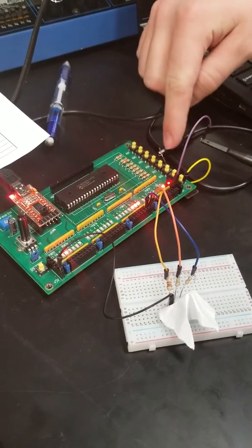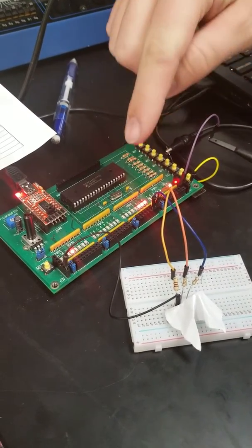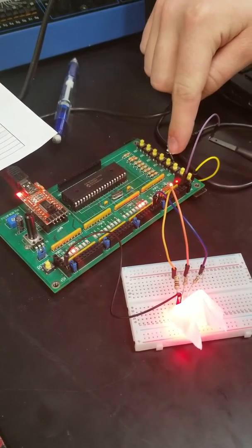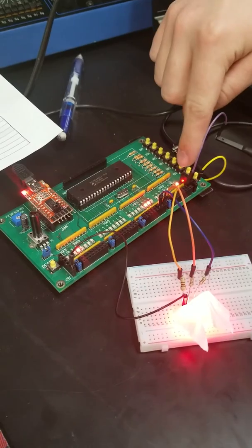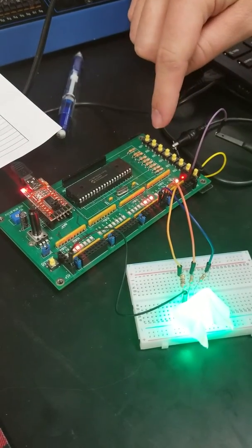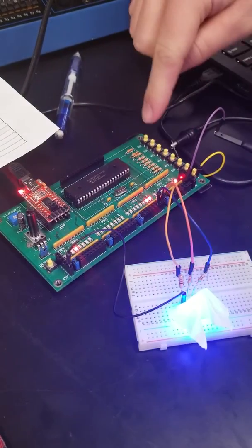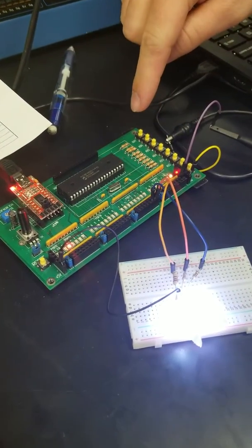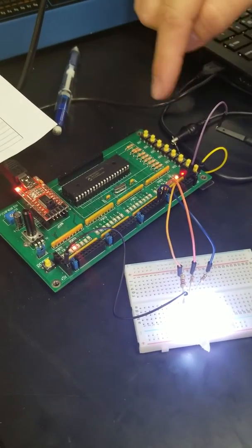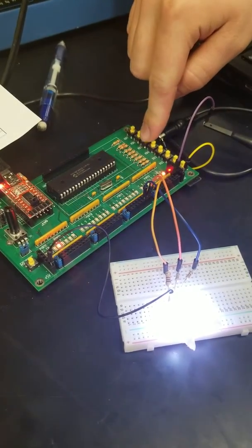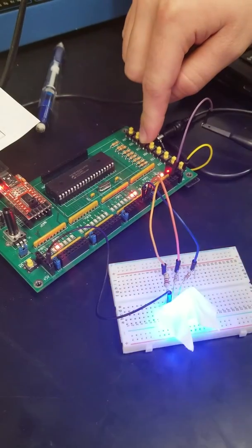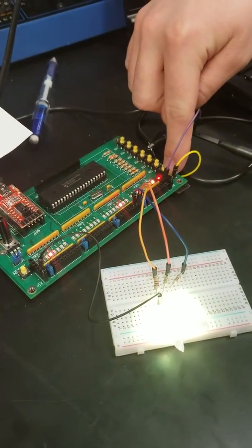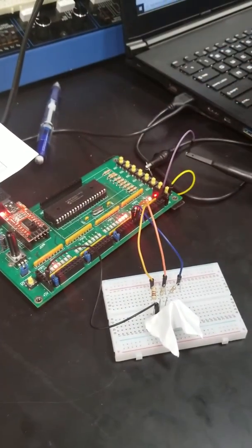So as you can see right now, we've got them all off because there's 5 volts here, 5 volts there, no voltage differential. Then when we hit RB1, that drops that bit to ground, gets voltage across the red. Next, that drops that bit to ground, gets voltage across the green. Next button, drops the last bit, gets voltage across blue. RB4 here drops them all, so we've got voltage across all of them equally, looks white. And then our random one here can get all sorts of colors and all sorts of numbers over there, all mod 8. And then RB0 puts them all high again and turns them all off.